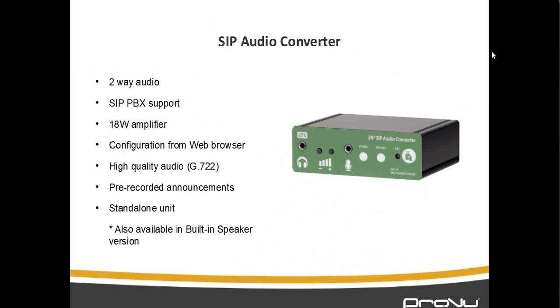What makes this one unique compared to an IP audio decoder is that it has a web browser built in, so you can configure this from a web browser. So you don't need the net speaker software or audio manager software for this one. You plug it in and it will get an IP address. You log into the web interface, configure a SIP account, and then it will purely just convert that SIP traffic into audio. So this is more like a purely SIP to audio converter.